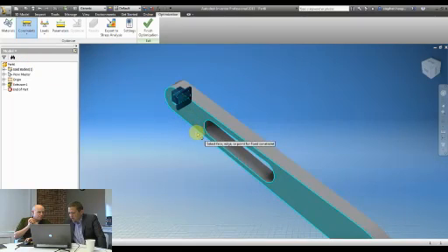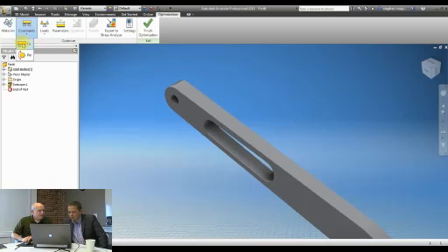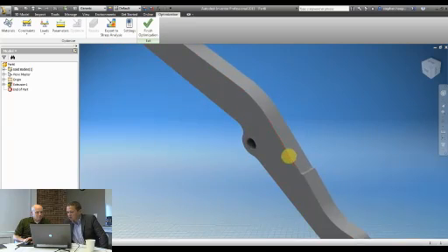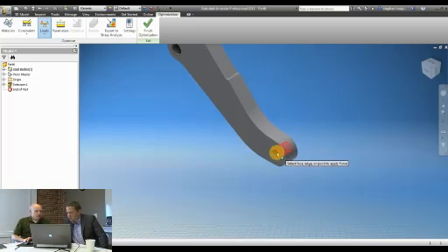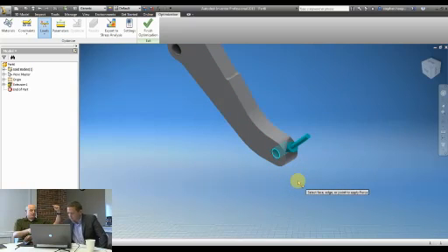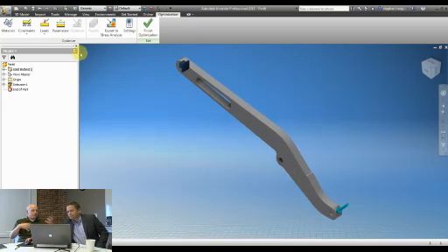No, we're going to define what it is that we do on the desktop, but first of all we're going to tell it where the model's actually fixed, so we're going to choose the back there. And then what we're going to do is place a load onto the model, so we're going to tell it where the force operates. So at the top is fixed, at the bottom you're going to have the pressure, and now we're going to figure out, okay, so what parameters are we going to test? That's the next bit that we're going to do.